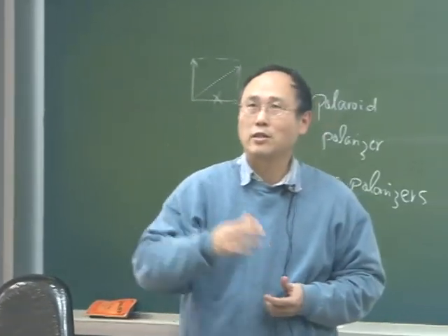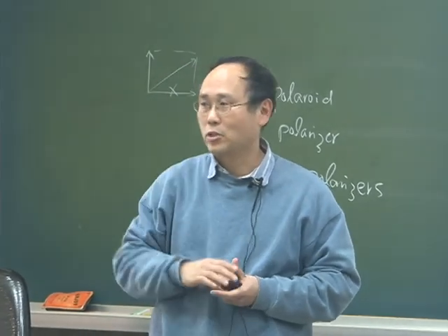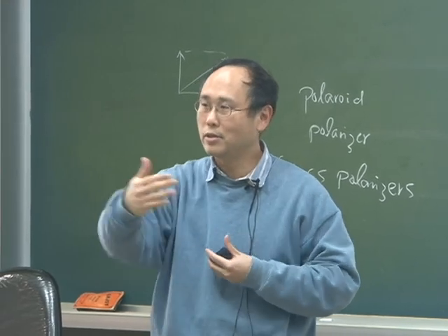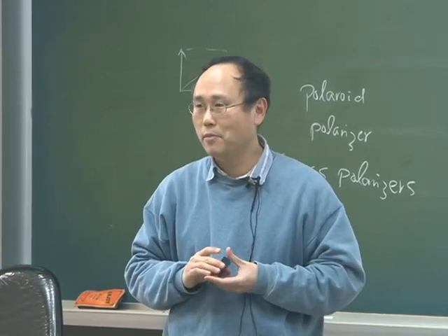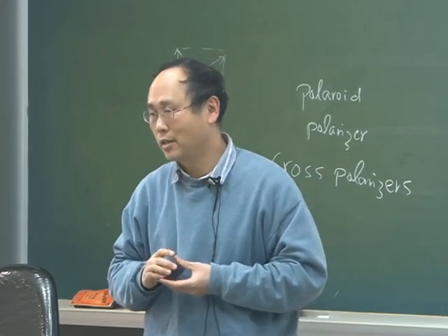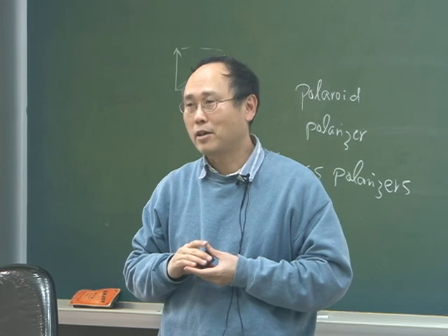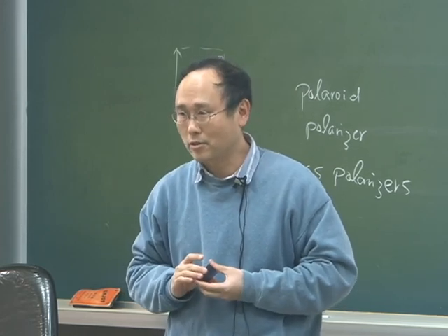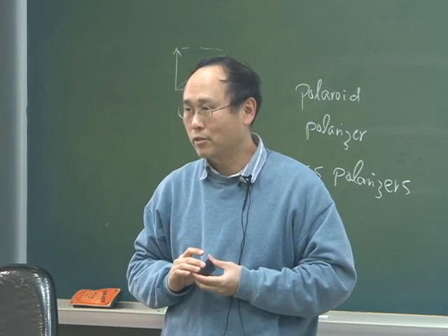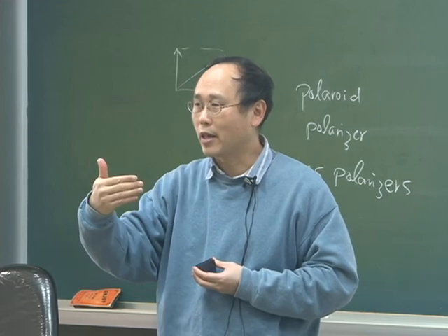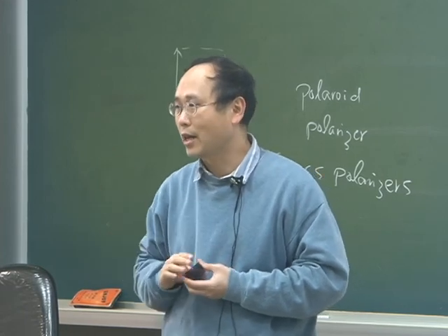Another example is this projector. Same thing. There's a light in the back of this projector, and then the light goes through some LCD elements, and the LCD control the polarization direction of the light. And in front of this projector, there are polarizers. For different color, you have different polarization element to control, to absorb the light or transmit the light.